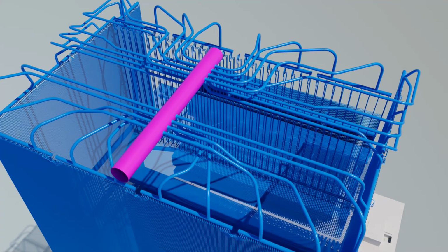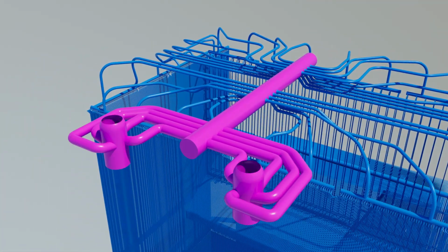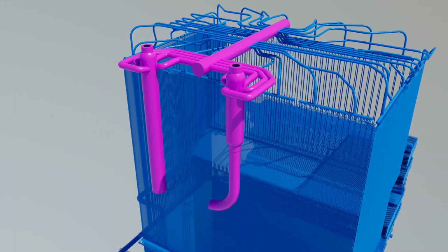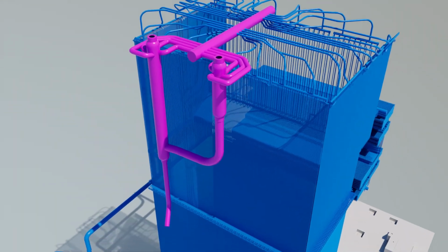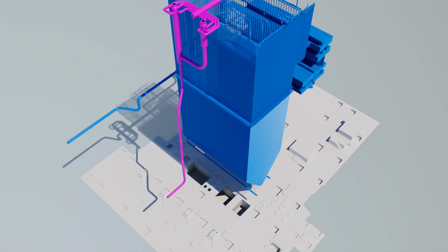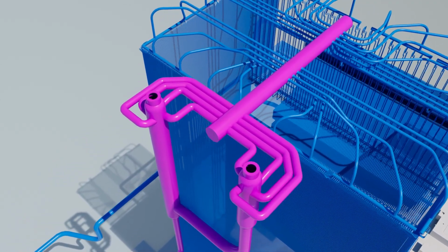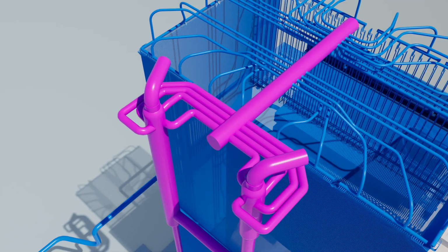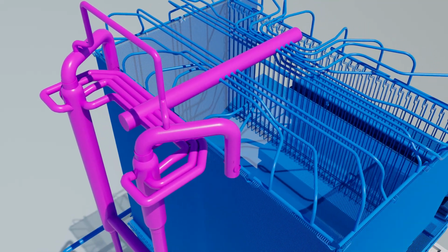The separator and separator drain tank separate the water-steam mixture into saturated steam and saturated water during the startup. The separator is of the cyclone type and is provided with 4 inlet connecting pipes in tangential and downward direction installed on the separator body.